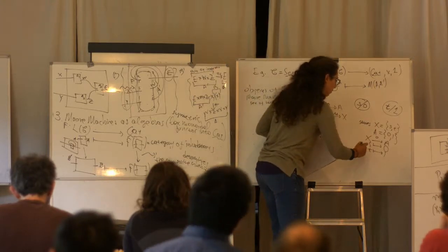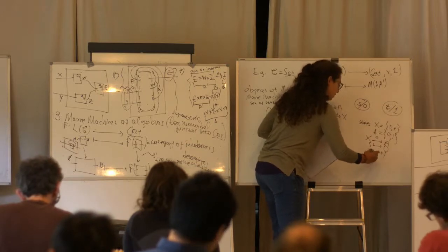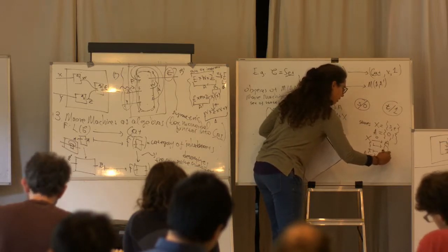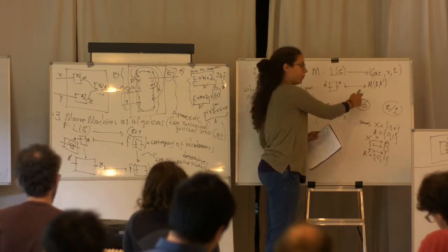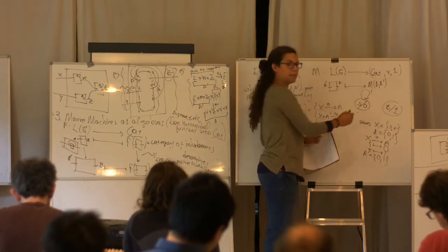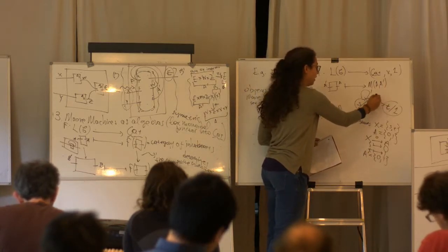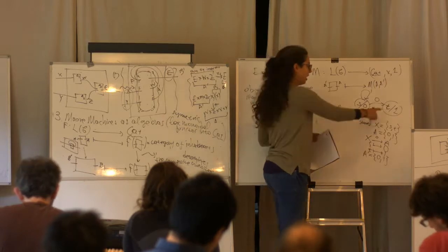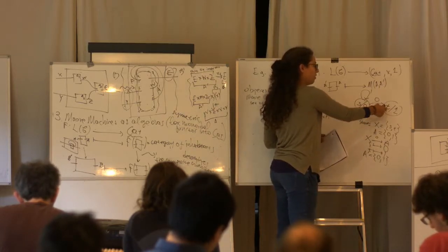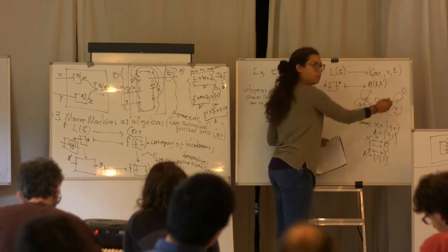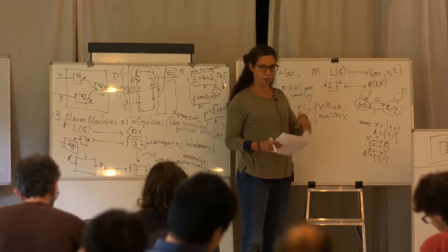And now I'm going to give the input set, which is the same in this specific example, 0, 1. And what I'm going to do now is say, whenever this state S receives a 1, it stays where it is. But whenever this state receives a 0, it goes to the other state T. Now for T, whenever this state receives a 1, it goes back to S. And whenever it receives a 0, it stays at the same state. So this is a very common Moore machine or finite state machine depiction of what's going on.